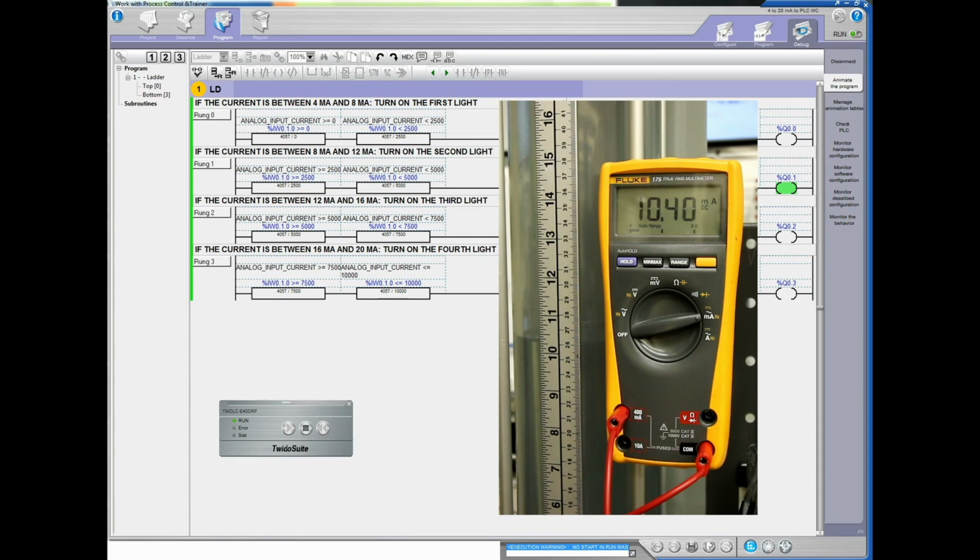Okay, let's drop her down again to 20 centimeters. We should see 8 milliamps. Very nice. Okay, so we got what, 7.96? That's beautiful. And we should be at 2,500. We're at 2496. So it just jumped to the final LED there. So I'm a little bit shy of 20 centimeters. So it just jumped from the second light down to my first light. And from here all the way down to 10 centimeters, that first light should be on.